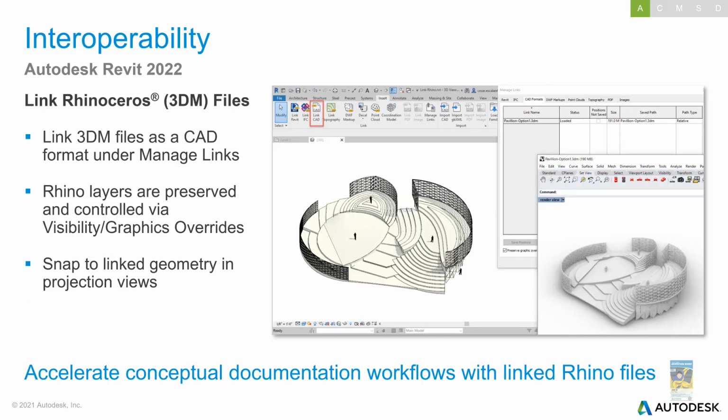If you're working with Rhino files, you now can bring Rhino files into Revit as a CAD file, and you can preserve and control those layers via the Visibility Graphics dialog box, and it actually snaps to the geometry as well.